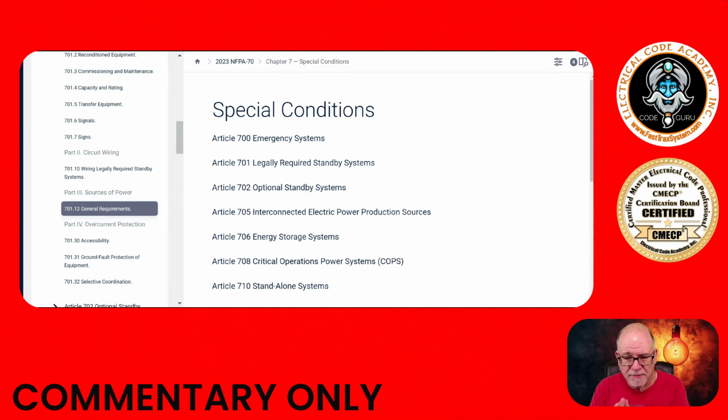Now, if you don't know that, I'm going to tell you something that's really important here. When you know that an article is very small, and you just do this by getting used to it, like Article 320 is small, 330 for MC cable is small. It's not as expansive as 430 for motors, okay? But 430 has its own little pictograph right in the beginning to help you maneuver yourself. When you have these smaller articles, it's not necessary. For example, I could go hunting in the index for all kinds of little things, or if I already know that I'm in Article 701 and that it is a very small article because I've been studying, then I'm going to go straight to 701.